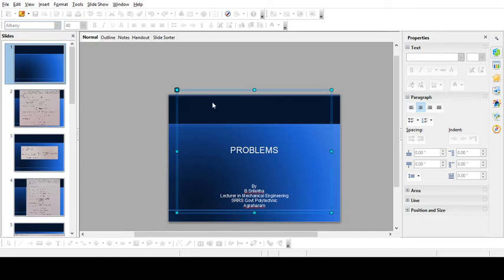So we already know that Poisson's ratio is 0.25. It is given in the problem. Next, length of the flat is 250 mm. Next, width is 100 mm. Next, thickness is 50 mm. Now volume is simply L B H or L B T. So it is 50 into 100 into 250. It is equal to 125 into 10 to the power of 4 mm cube.